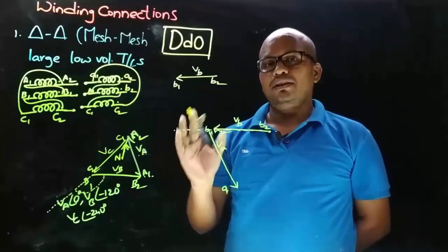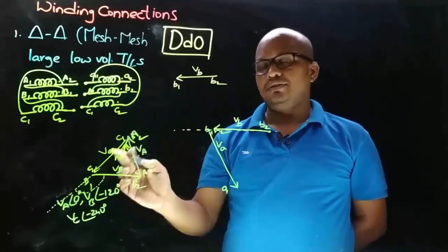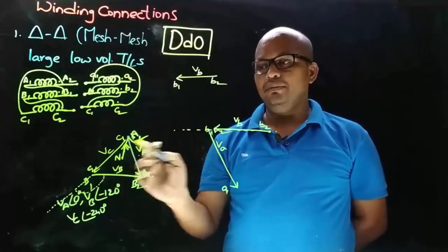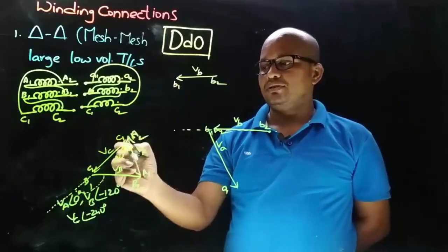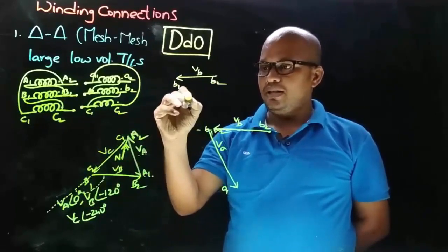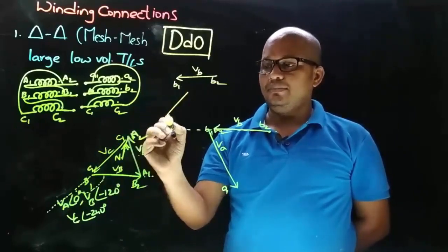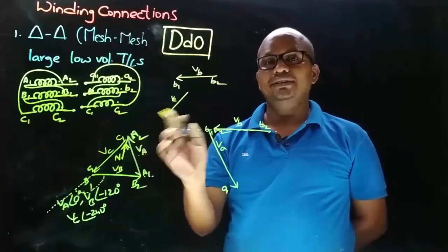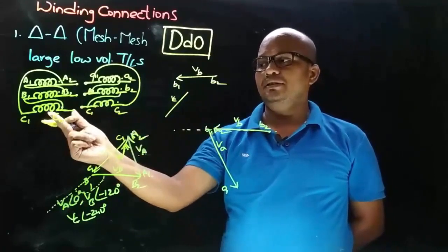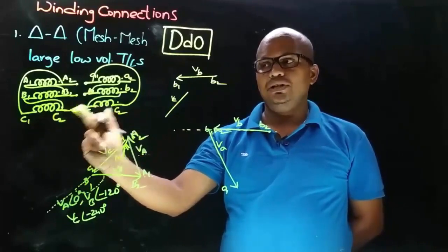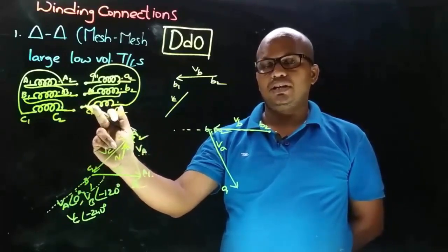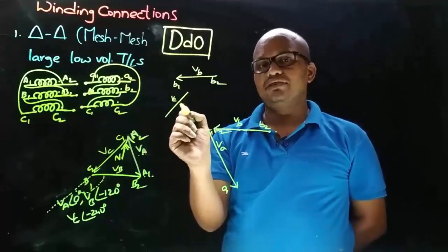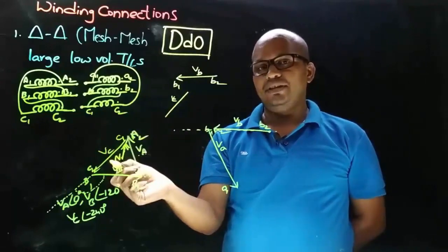Okay, now let's draw the second side VC phasor. So second side VC phasor is drawn parallel to primary side VC phasor. So primary side VC phasor is like this. So let's draw the second side VC phasor parallel to primary side VC phasor. Okay, and now we need to decide the direction. So here primary side is took from dot end and on secondary side the connection is took from non-dot end, means opposite direction. So secondary side VC phasor will be opposite to primary side VC phasor.